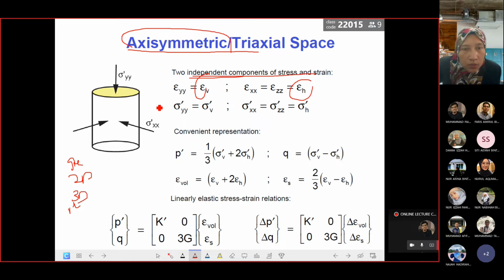Somehow what are the differences between these, contohnya kalau you ambil plane strain, you ambil plane stress ataupun you ambil axisymmetric, dia punya stress component assumptions tu yang berbeza. So they will finally affect the final results bila you buat simulations. So final results tu lah yang menceritakan kepada awak adakah input for the first one you set tu you masukkan betul ataupun salah.